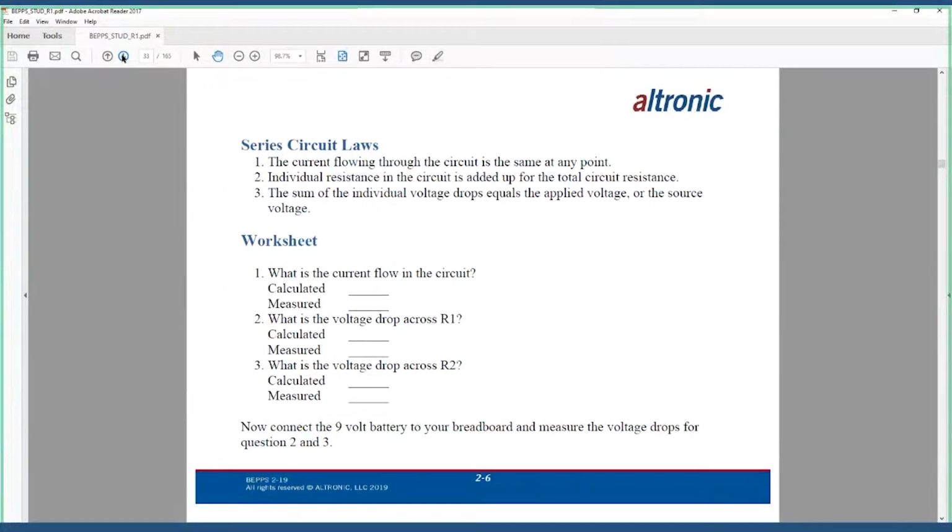So what we're going to do is take amperage, and see if I wrote that down right. Voltage 9 volts divided by 2,000 ohms equals, I'm sorry, I knew I put another decimal in there, 0.0045. So now that's our known amperage.